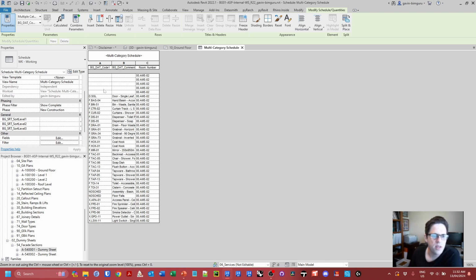So we can start to filter. Now we can either use an inclusion filter or an exclusion filter. If I just wanted to target all my furniture, you'll notice all the furniture in my system is F dot. Now this is the value of designing your data systems to work well. In my case, I made some very early decisions in my system design where I said all my furniture and fixtures will begin with F dot. All my joinery will be J dot. All my services will be X dot. And that really helps me move my data very quickly, filter it, do all sorts of things with it, both in Revit and also in Dynamo. Not everyone makes those choices in companies, so you have to be careful.